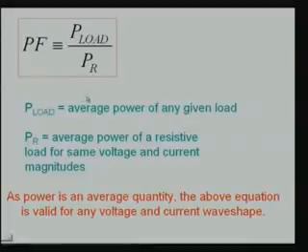Again, summing up, the power factor, Pf, is defined as P load, the average power of any arbitrary load, the active portion of the power given to the load, divided by Pr, which is the power that you would have delivered to the load if the load had been resistive.